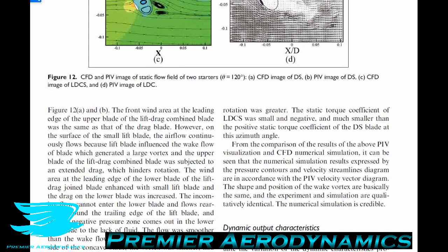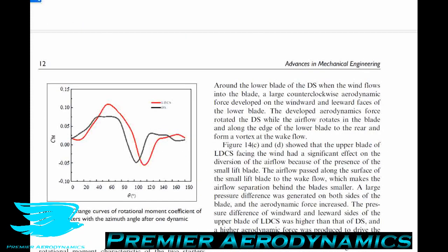So we looked at the torque the blades produce when they are just static and just starting up. But what about once we have 1 revolution, because that is also part of the startup phase. In figure 13, we see the rotational moment coefficient of the drag only blades and lift and drag blades. For this figure, the higher the better. The more torque the blades produce, the greater the moment coefficient, and the better the blades are performing. Now we see quite a different story, where the lift and drag blades are better.